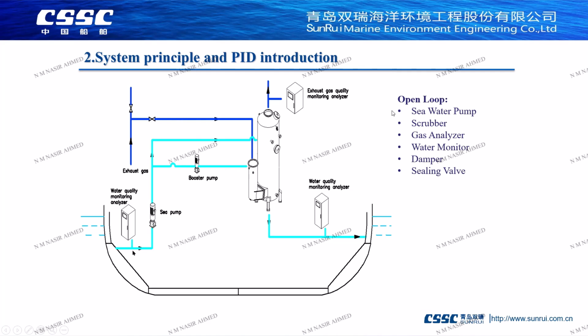The seawater passes through the sea pump, and the main part goes into the scrubber to wash the smoke. Another route goes through the pre-spray pump into the auxiliary tower to cool the flue gas. The flue gas, after washing, is discharged directly into the atmosphere, and it is detected before discharge to check whether the value of the emitted smoke is up to standard.